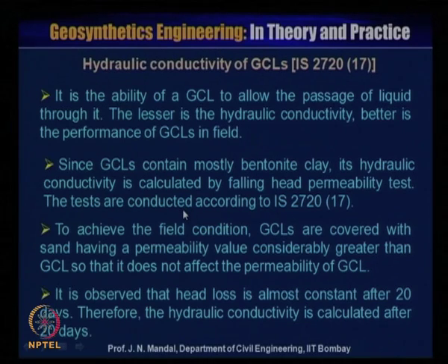Now, hydraulic conductivity of GCL as per IS 2720-17 is the ability of a geosynthetic clay liner to allow the passage of liquid through it. The lesser the hydraulic conductivity, the better the performance of GCL in the field. Since GCL contains mostly bentonite clay, its hydraulic conductivity is calculated by the falling head permeability test. These tests are conducted according to IS 2720.